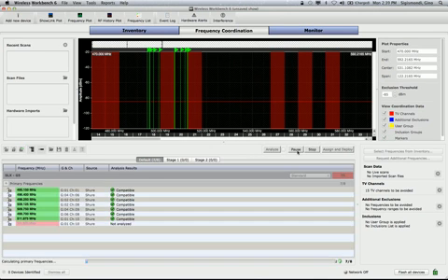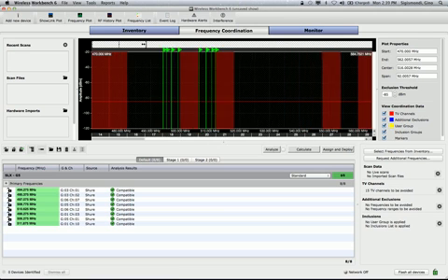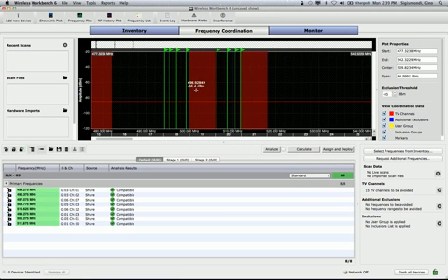And I can calculate a number of different solutions. Each one might look a little bit different. But you'll see that the frequency markers in this plot view get distributed in a way such that none of the TV channels we aim to avoid are being overlapped by the frequencies. And the frequency placements themselves are all compatible with one another. So this achieves 2 things. One, inter-system compatibility. The frequencies, while they might look random, are mathematically sound not to create intermod products on top of one another. And 2, to the best of our ability, we've avoided RF interference from the outside world, TV channels being the primary source that we're able to take care of.